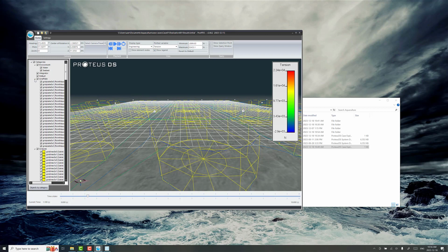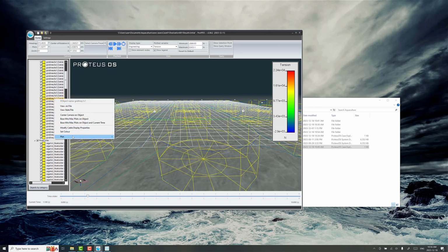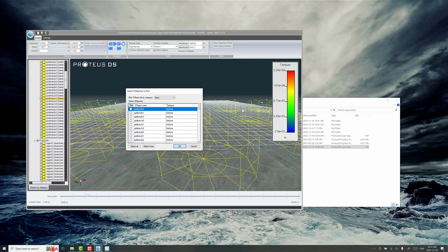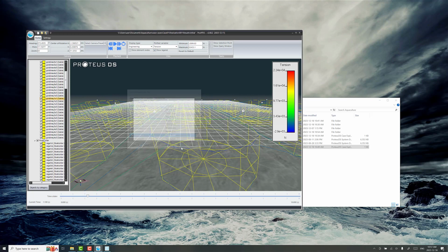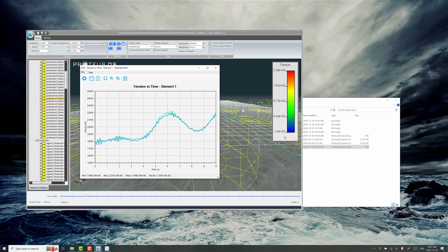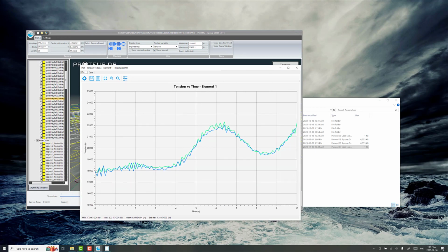And again, we can do plotting. If we pick any line here, we can go plot tensions. If you recall from last time, lines 19 and 18 were the most loaded, just from visually looking at them, and we'll pick those two to make our plot. Remember, N1 is at the grid. You can see the pre-tension values from current, then from the ramping up wave there's a little bit of dynamics, and then we're seeing maximums around here.